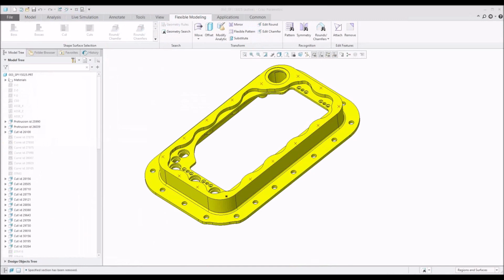Okay, so the intelligent fastener stuff is basically using UDFs in the background as well. So yes, you can, but you'll have to take that information that you already have in your UDFs and take that over to the IFX library. So if you already spent a few hours on creating UDFs, that information unfortunately will have to be carried over to the IFX stuff as well. So you'll have to open up the text files and add that information in there as well.